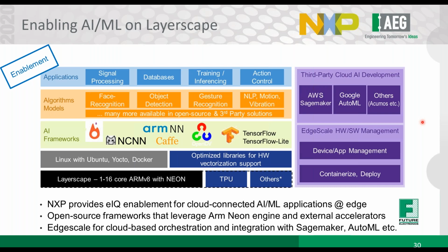And then also if the CPU performance is not sufficient, as JP was mentioning earlier as well, we do have the ability to add external accelerators for AI machine learning. These can be connected through either a USB interface or a PCIe interface, depending on what type of device and what type of modules might be available. And these can give you significant improvements in performance as well, depending on the kind of inferencing performance those devices can support. It can range anywhere from maybe 10x to 15x performance improvement versus running that same model on a CPU platform. So a lot of different options there.